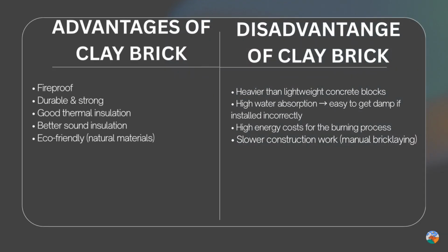Advantages of clay brick: fireproof, durable and strong, good thermal insulation, better sound insulation, eco-friendly, using natural materials. Disadvantages of clay brick: heavier than lightweight concrete blocks, high water absorption, which makes it easy to get damp if installed incorrectly, high energy cost for the burning process, slower construction work, manual bricklaying.